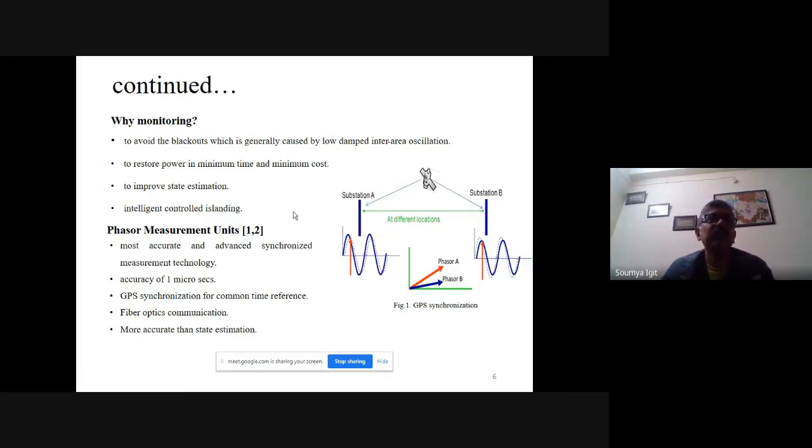Now the question is, when I talk about the 2012 blackout, have you really analyzed the northern grid, the transmission network, how the blackout and the catastrophic failure occurred in that system, which was rooted in the overloading of a particular transmission system? And what is the root cause of the malfunction of the zone 3 backup? Because it is the ultimate line of defense of the protection system in the transmission network, and if zone 3 fails, the catastrophic failure and cascaded outage occur.